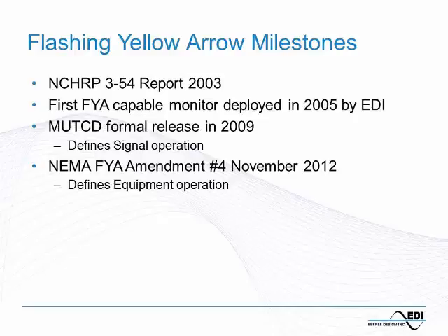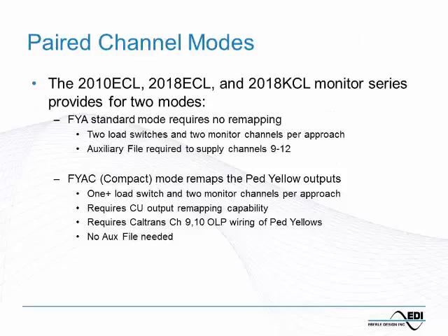The flashing yellow arrow has a red arrow, solid yellow arrow, flashing yellow arrow, and solid green arrow. So one of the problems here is trying to get 4 signals monitored with equipment that is intended to drive 3 signals. So we'll get into how we do that.